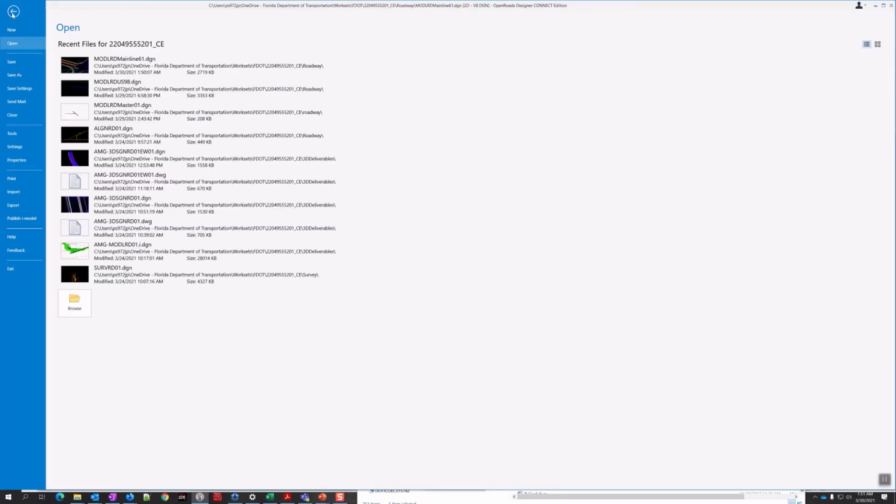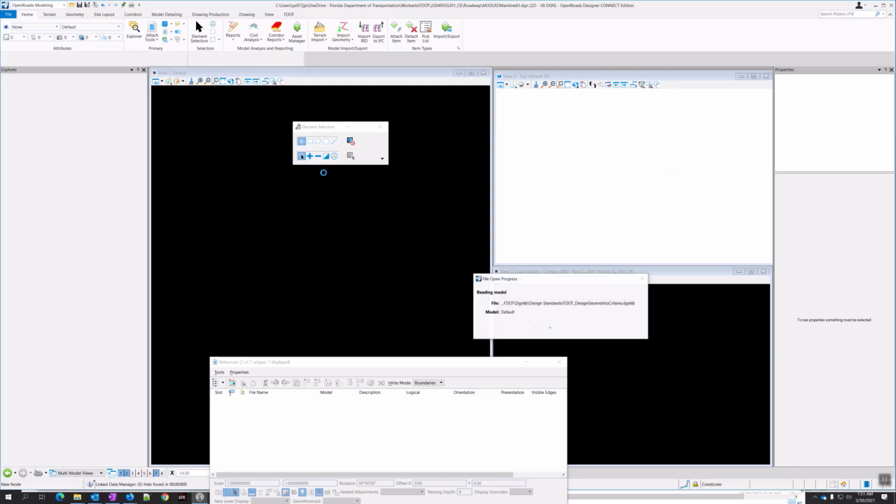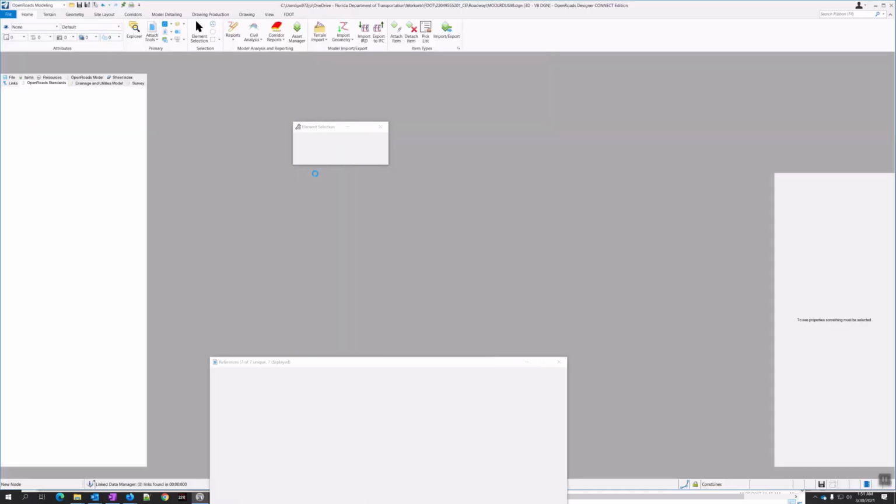We're going to open up the US98 file. It's at the bottom of the same page. Just go to create cut and fill volumes for US98. So we're going to open up the US98 file, and we're basically repeating the same steps. And that includes adding the existing features. So let's make sure that's added if it's not already on there.